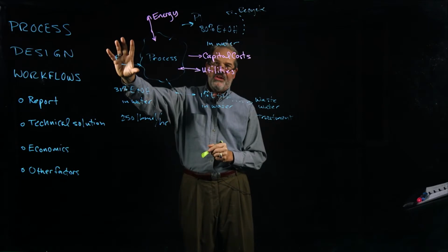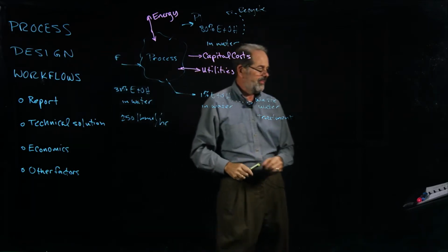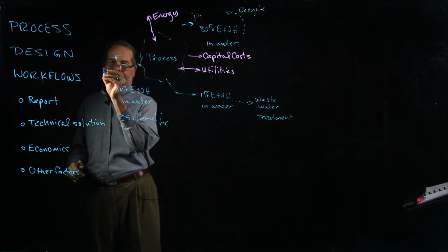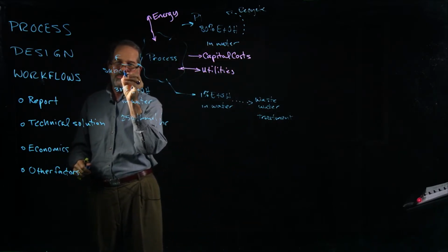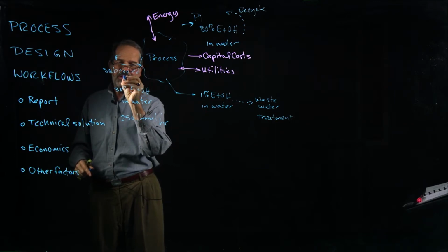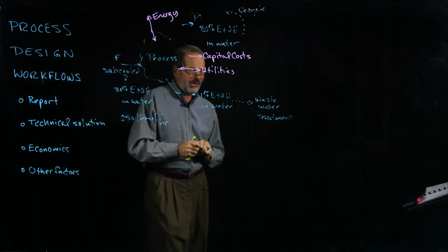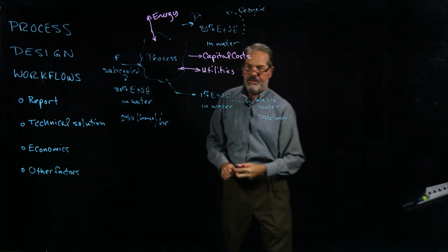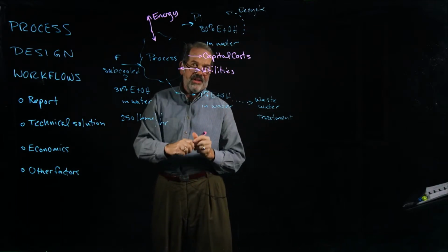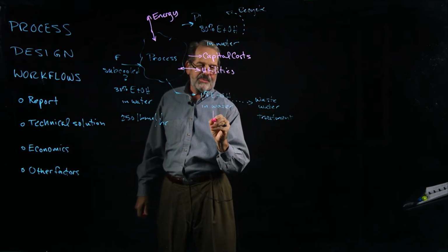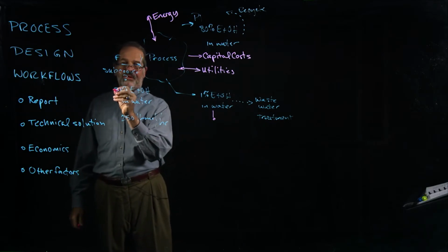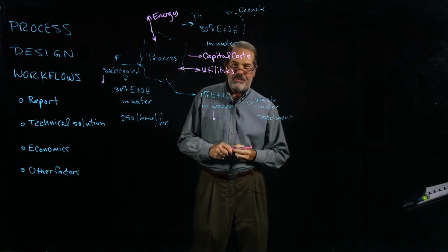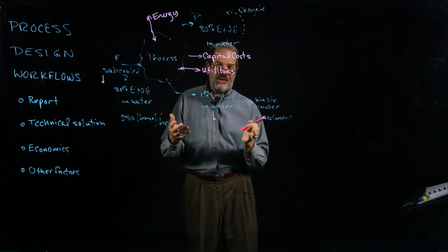The client has also specified a feed which happens to be subcooled. And I'll put a question mark there. So we've got two client specifications: 1% ethanol as a product, I'm going to put a surprise there, and a subcooled feed, I'm going to put a surprise there, which may not be optimal for either the client or for us.